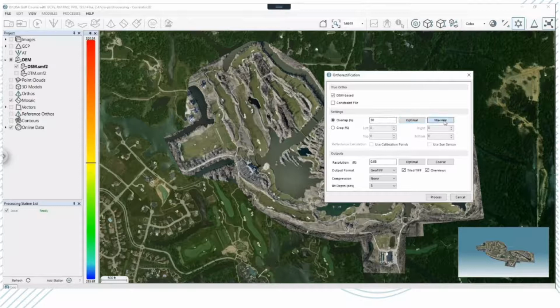And then below that, when we start talking about large format aircraft, where we talk about the crop percentages, those are left over from the days when you used to have vignetting from cameras inside of aircraft bellies. You could crop, or you could crop out fiducials, things like that. So typically we would not do that unless you were working with a large format camera, then go for it. Or if you notice vignetting from your aircraft. So be aware of that.